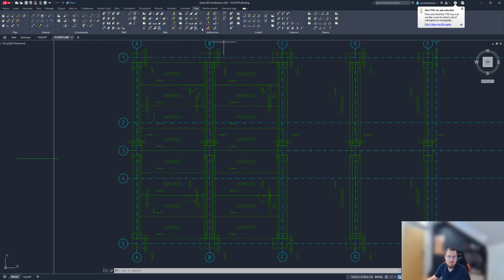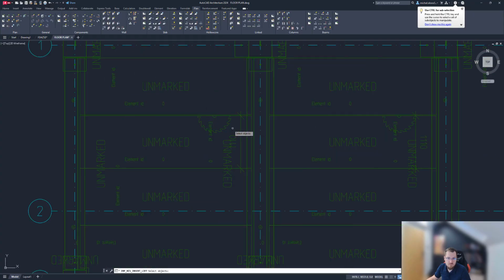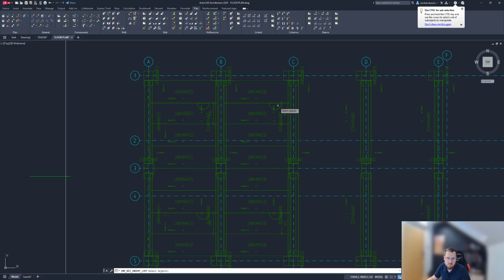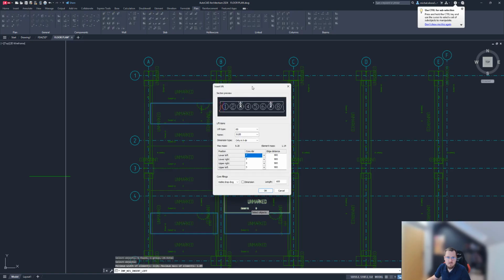One more thing. We're going to actually add lifts to some of those. You can see we have two cut slabs, so of course this side cannot be caught by a hook. The side with a saw mark, of course, a saw symbol, cannot be caught on by a hook. So we'll just manually add lifters to those hollow cores. There's an option.